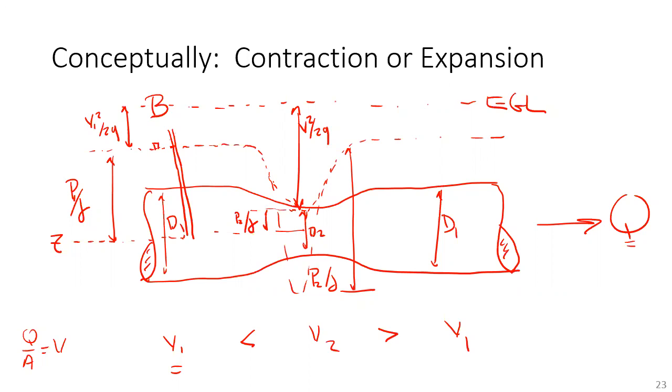Is there a limit to how low the pressure can go? Vapor pressure. So I've made this example before. You take a running hose of fluid, your garden hose, and you crimp it, and you hear the hissing inside of the hose. What you've done is driven the pressure in the system to below the vapor pressure, and you've cavitated the fluid.